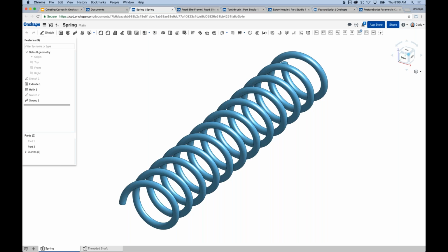A question that's been asked is, how about a conical helix? Absolutely. You would use a conical cylinder shape to define the actual helix. The example you give is a perfect one. Pipe threads are tapered and therefore would need a tapered cone to define the helix definition. And you can do that.